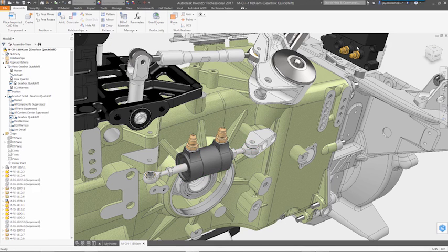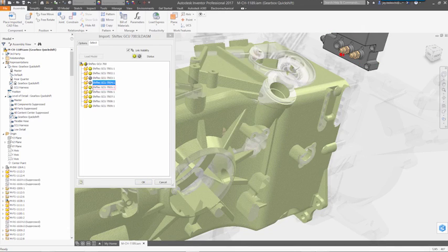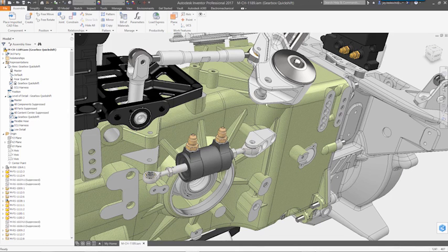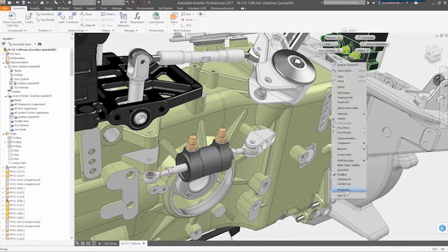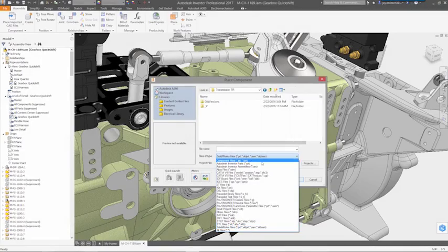Autodesk Inventor changes the way you work with non-native data. With AnyCAD technology, instead of translating files, you just open them using the reference model option. You can insert parts or subassemblies into your designs error-free while maintaining a link to the original file. Templates can be created for mapping properties from the source file to standard Inventor properties, with the ability to override or retrieve the original properties at any point.